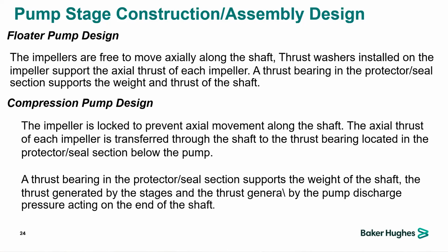So instead of having all of the thrust transferred to the seal section, it's absorbed inside the pump. After each couple of stages, there is a thrust bearing inside the ESP pump section, and the thrust is absorbed inside the pump instead of being transferred to the seal. But the impeller is free to move up and down, same as floater pump design.